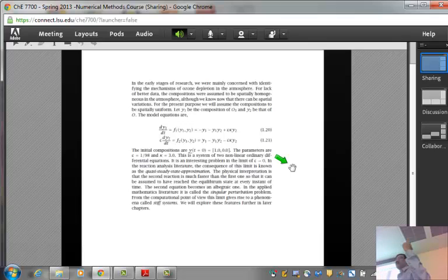Something that we have seen in the fluid mechanics course. A number of you have taken that from me, right? At that time, I mentioned this kind of a thing happening in reaction engineering. Do you remember what it is called? In fluid mechanics, we would call that boundary layer theory, right? A differential term multiplied by a small coefficient, viscosity, for example. When we say the viscosity is 0, then we throw out the viscous term completely, and we get the Euler equation, right? So here we are saying that epsilon is close to 0, so we are going to throw that term out. We can never do that, but we tend to do it because it simplifies the analysis, and this is called the quasi-steady state approximation in reaction kinetics.